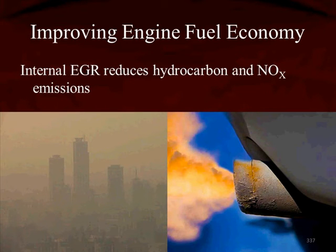For example, here we can see that we have a tailpipe pumping stuff into the atmosphere. In this picture we can't tell exactly what's in it, but it sure looks like some bad stuff. In order to reduce HC and NOx coming out of the tailpipe, VVT, variable cam timing, variable valve timing, can give us internal EGR.